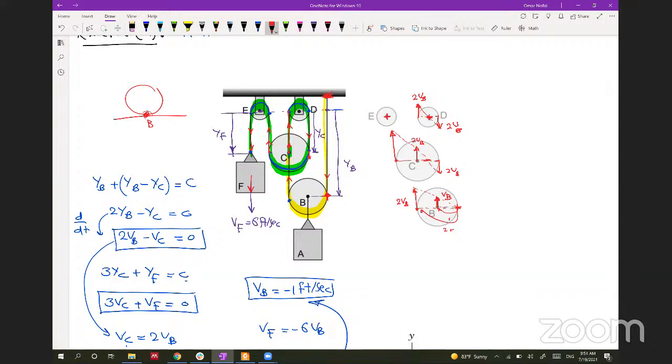And actually, this is the instantaneous center of zero velocity here. So you have 2VB here and 2VB here. If you solve this triangle, you will find that the velocity at the end will be 6VB. You can solve it easily. So this part is going to be equal to this one, and this one is going to be 4VB after you do some geometry analysis.